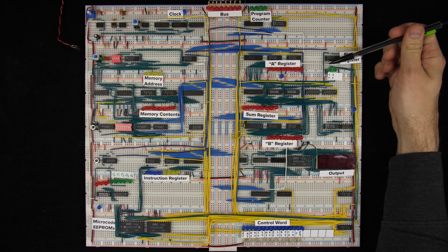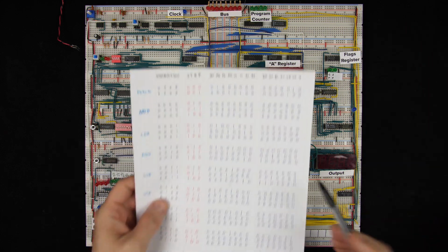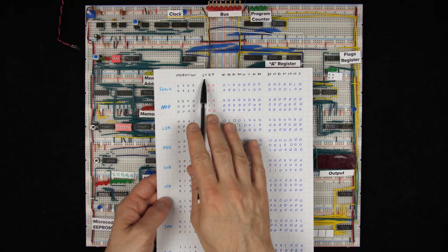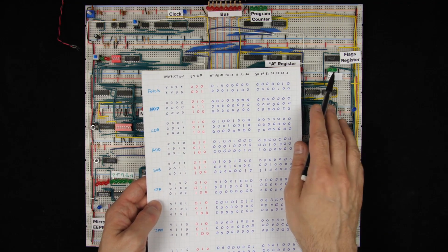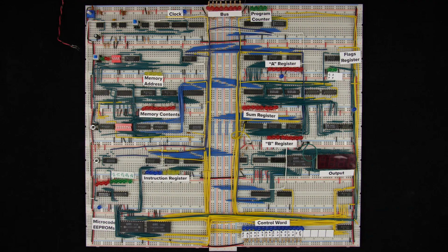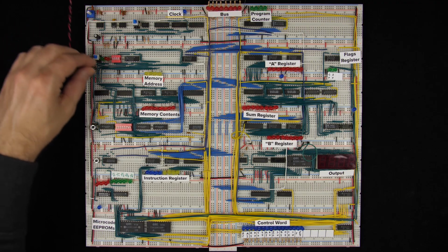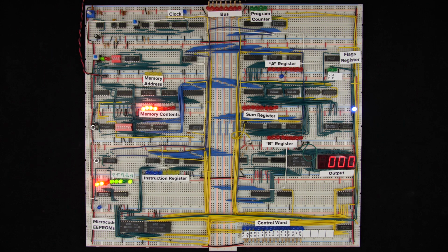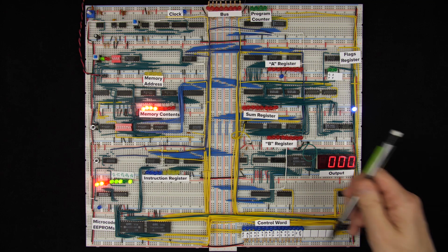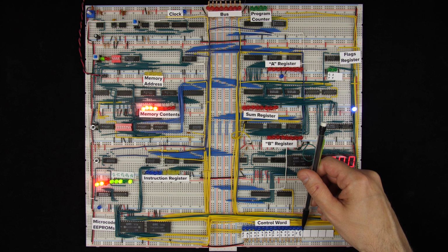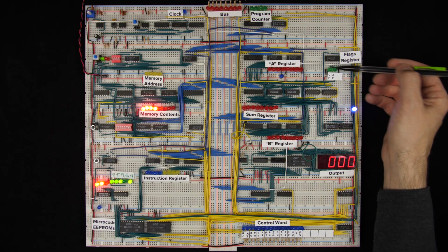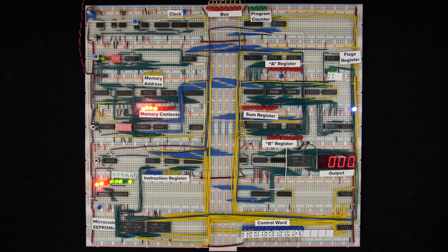All right, so now we've got the flags register hooked up as another input to our control word lookup table. So now our control word is going to depend on the instruction we're on, what step of that instruction we're on, and what the flags register might happen to be. Now, if we hook this up, as long as the flags register is 0, then everything's going to work out just like it did before. And actually, since none of our instructions are setting this flags in bit yet, because we haven't reprogrammed our microcode at all, the flags will actually always be 0. So right now, the computer actually works exactly like it did at the beginning of the video.